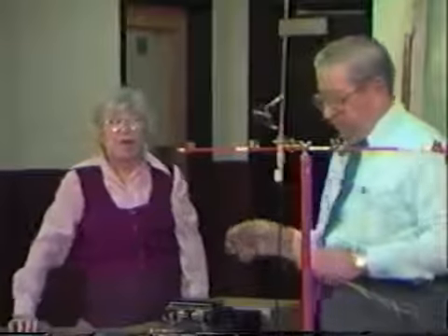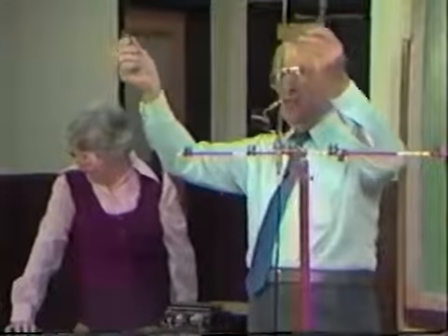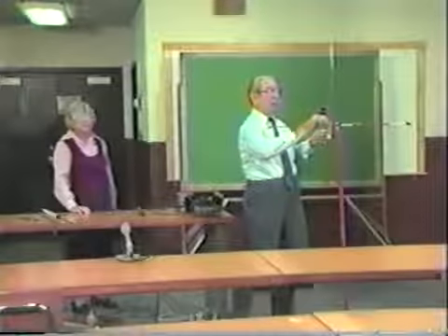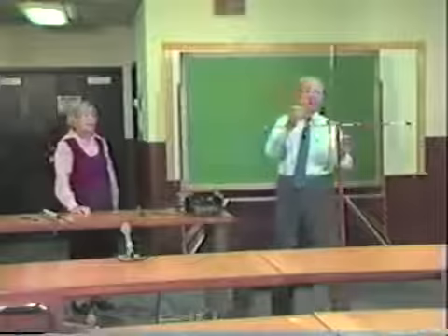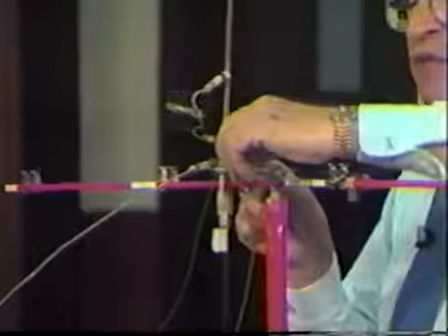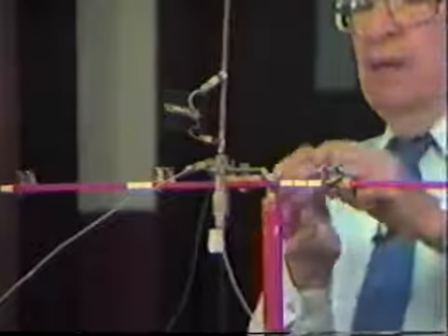Turn it off. I have here 4 pieces of wire. These are going to be our ground plane. These are the same length as our quarter wave vertical antenna, and I'm simply going to clip them on to a portion of the base of the antenna at the termination of the antenna. Okay?